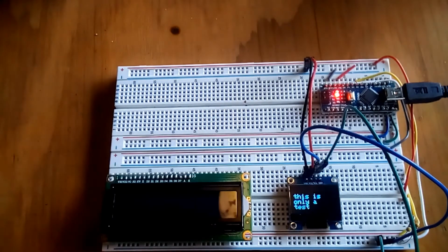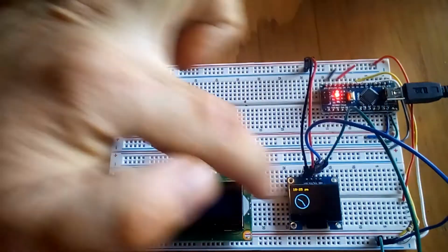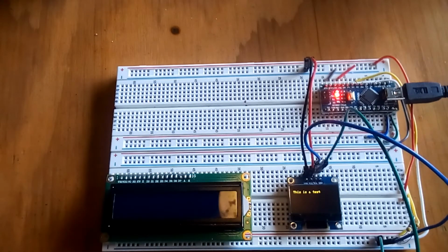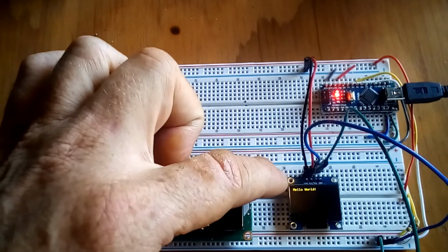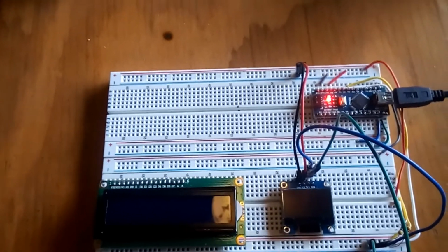But again, we're multiplexing this screen, so we turn on all the pixels in a row and flash through the columns really quick so that it looks like one single picture. This particular screen has 128 pixels across and 64 pixels down. And then we just control which ones we have. On this particular one, the first 16 pixels are yellow and the rest are blue, to help organize the data. It's showing a little bit better. But there's still, like the LCD screen, not a lot of color option on it. Just a way to show some text and graphics.